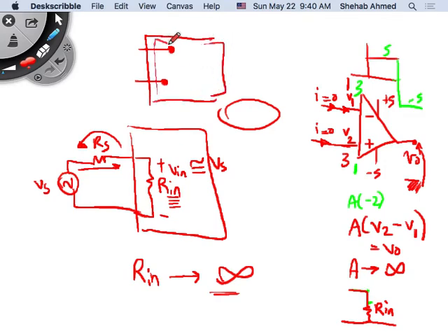Here, this is my op-amp. It's an open circuit. That's the ideal op-amp. So no current will come in, so the I equals 0, ideally. This is only for the ideal op-amp. So this is nice. This is excellent. We like this characteristic because it's not going to load my sensors and it will only measure the voltage that the sensor is producing.